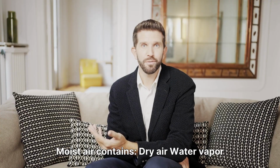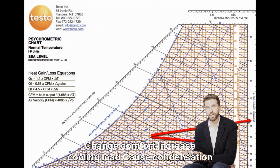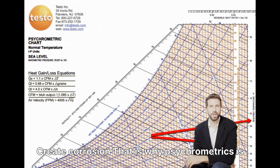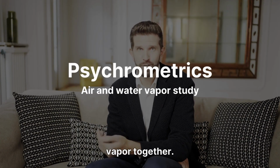Let's understand moist air. Moist air contains dry air and water vapor. Even a small amount of moisture can change comfort, increase cooling load, cause condensation, and create corrosion. That is why psychrometrics is so important. Psychrometrics means the study of air and water vapor together.